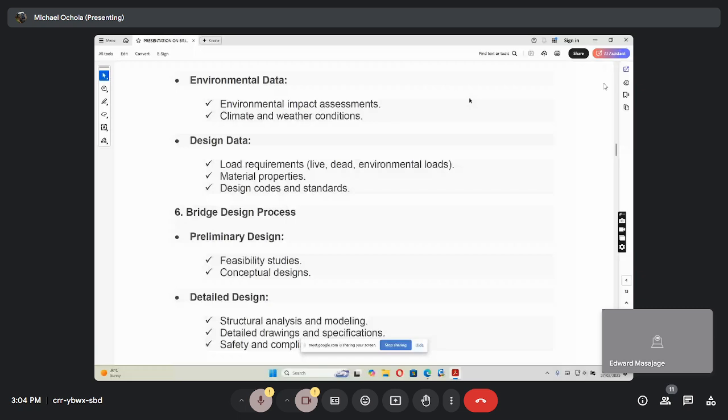So when you are modeling a bridge, which we're going to see at a later date, there's construction loading until a certain time. When the bridge has hardened, the concrete is set and the rest are done, then you start bringing in these additions, which we call finishes. In building, you call them finishes. Then there is live load from traffic and pedestrians,